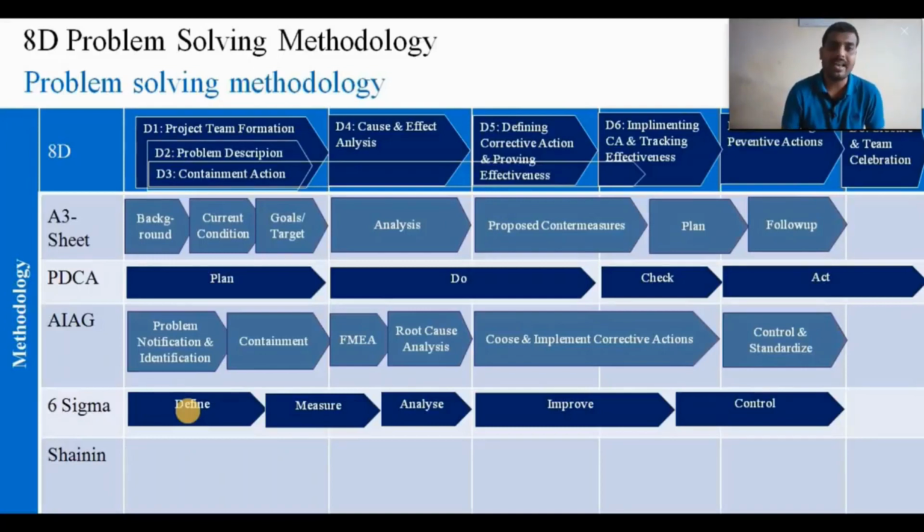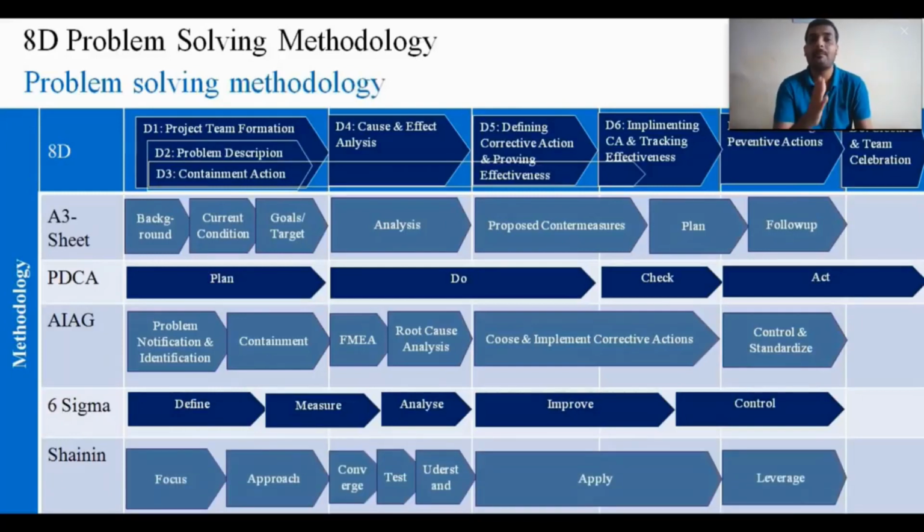and product reliability. This Shainin methodology was established by Dr. Dorian Shainin, and it uses an investigative strategy for identifying the root cause from the contrast of BOB and WOW parts. That is, best of best called BOB and worst of worst called WOW. This Shainin methodology is a factual approach which depends on the facts only.